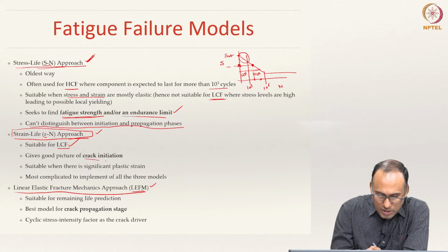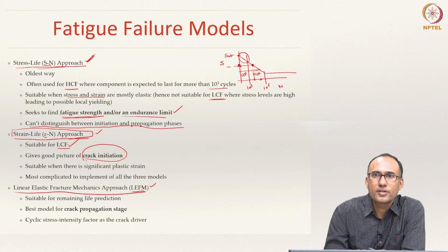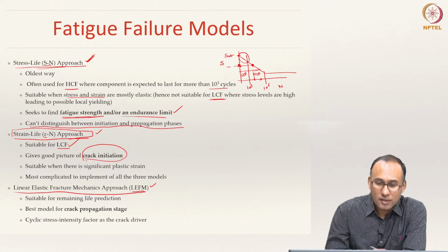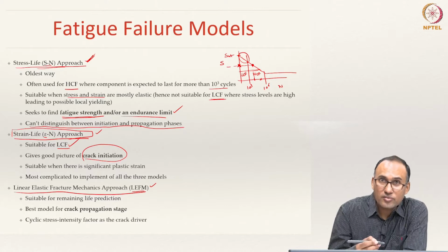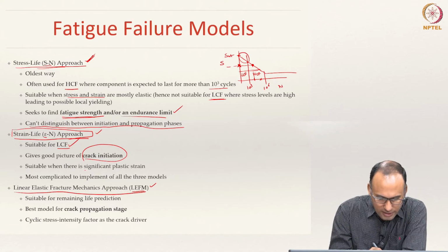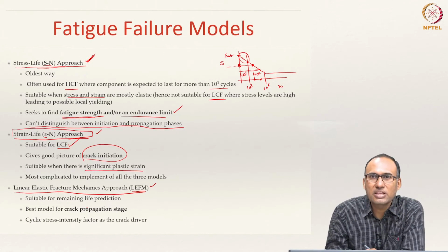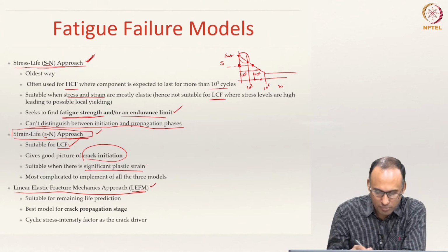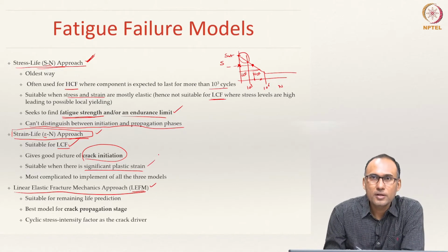It gives a very good picture of the crack initiation stage, and because we are dealing with strain, this model is particularly suitable when you have significant plastic deformation or plastic strains in the material.